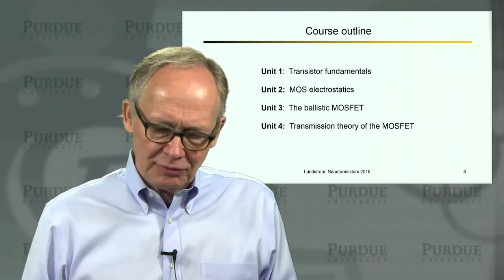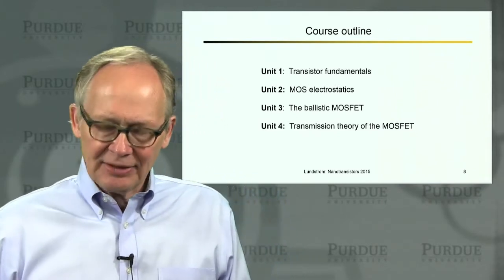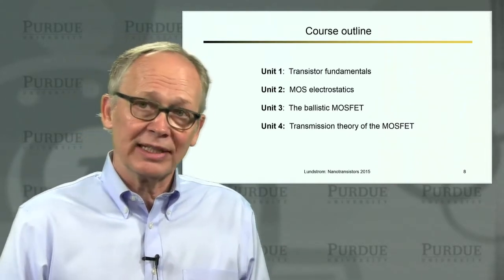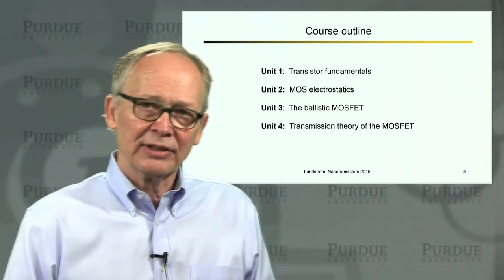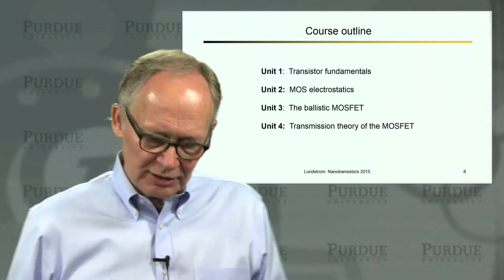And this is the full way of understanding transistors at the nanoscale. It includes the fact that some of them are going to scatter off of lattice imperfections and lattice vibrations and things like that. And this will give us a very solid but simple fundamental understanding of how these incredibly small devices operate.